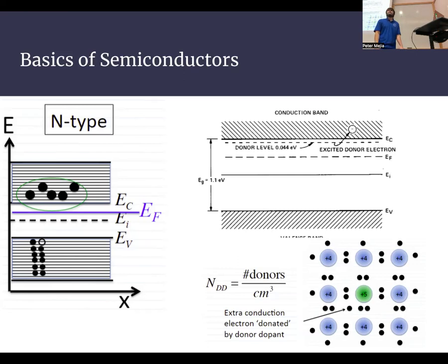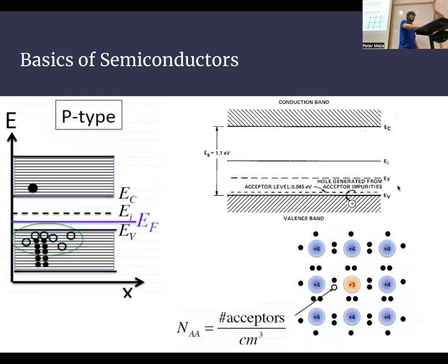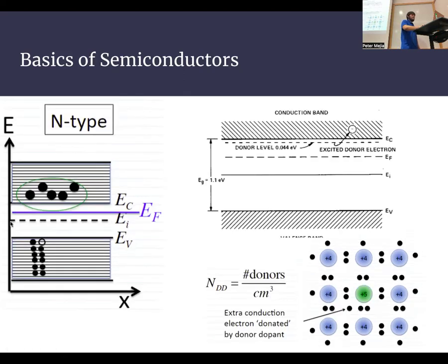What does the N-type bring up, the Fermi energy? The donor atoms supply those donor states, which are closer to the conduction band. It just has to do with the property of that extra electron. We can compare it to holes now. These holes offer an acceptor state, so instead of being at the top, close to the conduction band, it's close to the valence band. It just has to do with the property of the donor atoms.